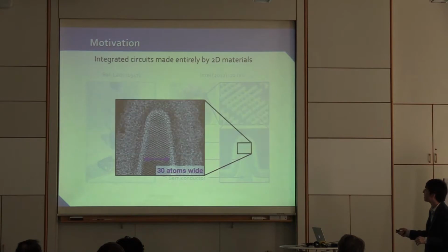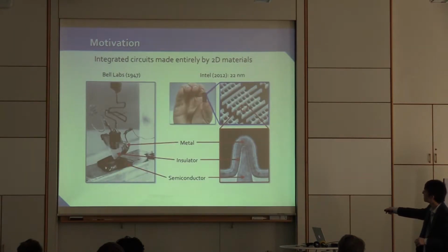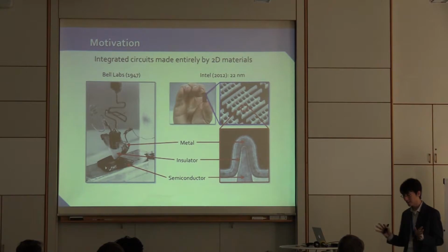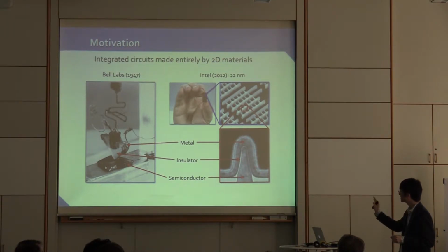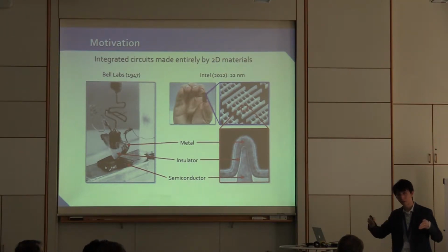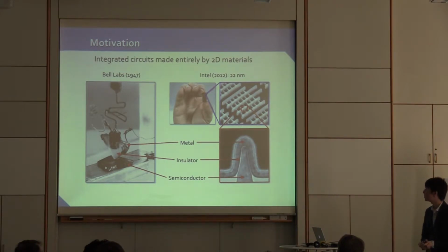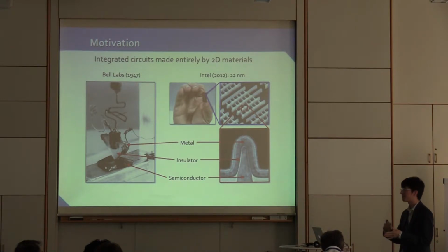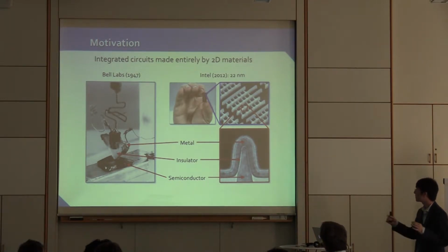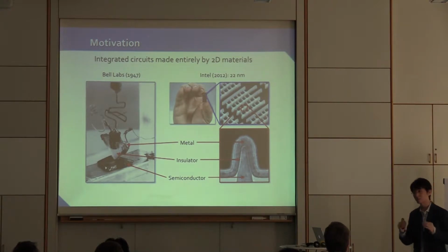If we make transistors smaller and smaller, they will face challenges such as quantum tunneling or source-to-drain leakage. This will be a problem, which can be costly, or basically reaches fundamental limits. One way to pack more transistors in a chip is to stack layers of many transistors. In order to do that, we need to find layered metals, insulators, and semiconductors.